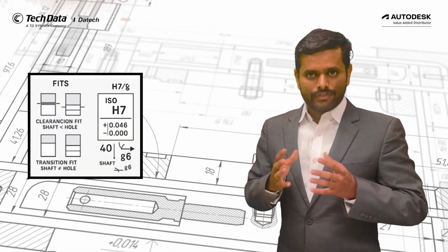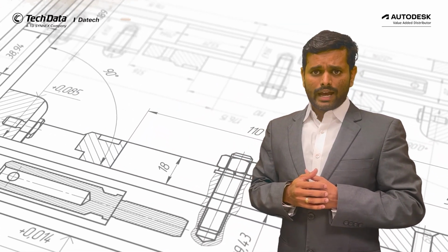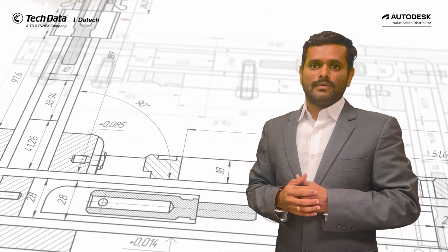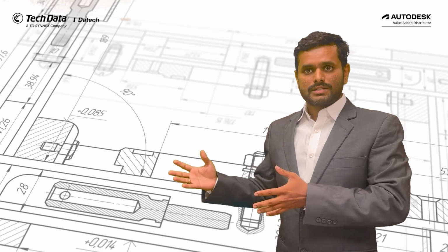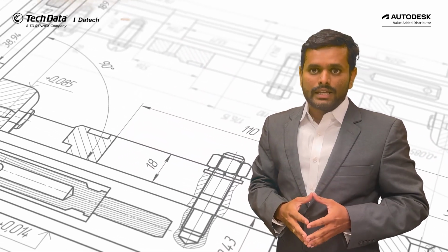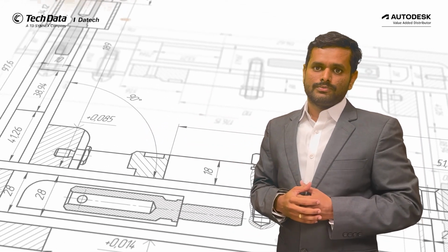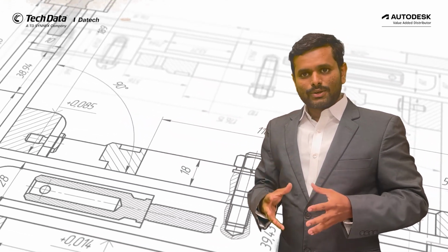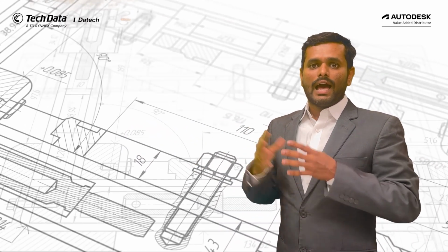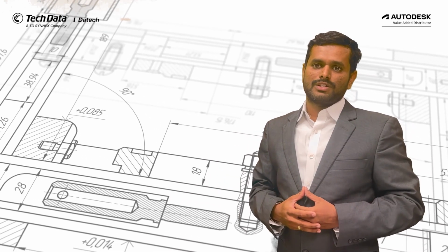You can add fits or tolerances to the dimensions and choose the representation from the list. You can also control the precision of the fits and tolerances independently of the precision of the dimension value. The drafting standard controls text sizes for the deviation automatically, eliminating the need for additional dimension styles.